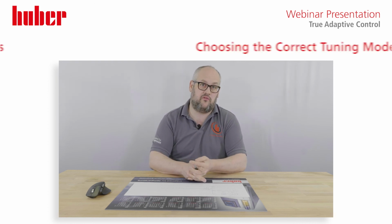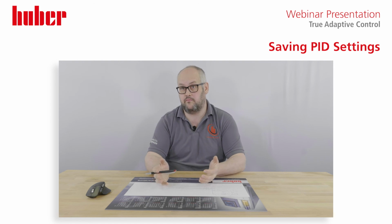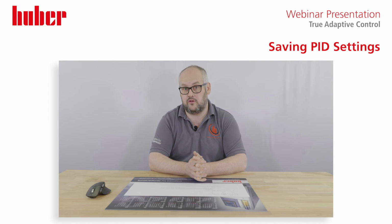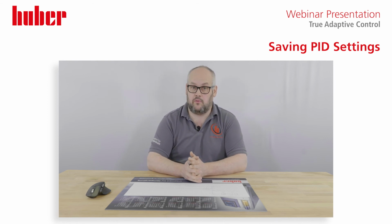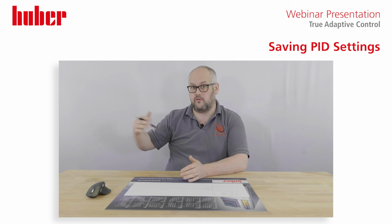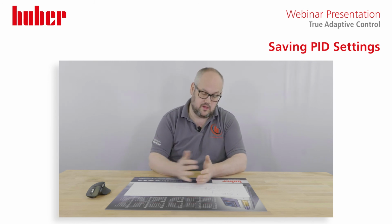A question we're often asked is, how many PIDs can I store in the system? I won't lie, the answer is 1, because you've got to tune to an application that you're running. The last thing we want someone to do is to apply incorrect PID values by selecting a second, third, or fourth option in the menu, and then they would lose a batch or something would be outside conformity. How do I get around that?